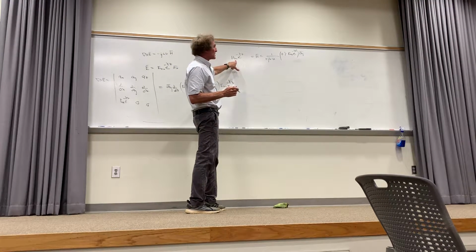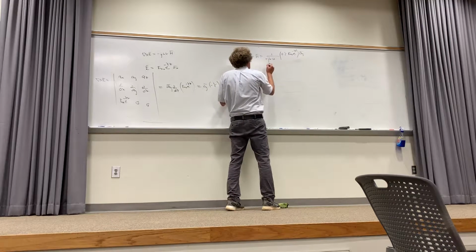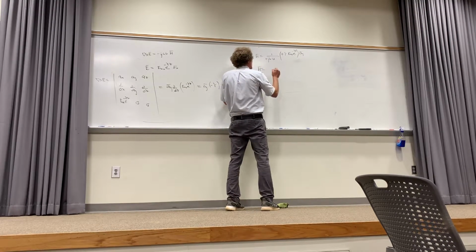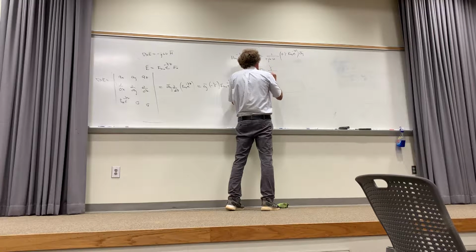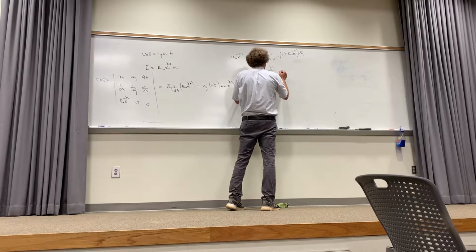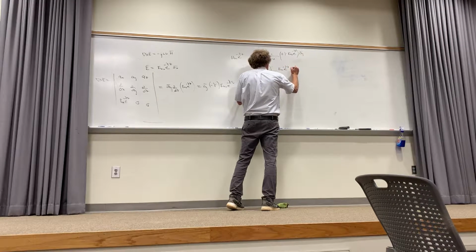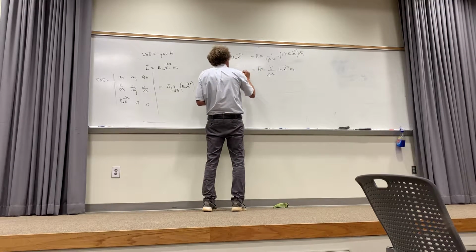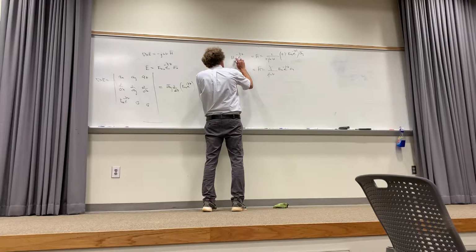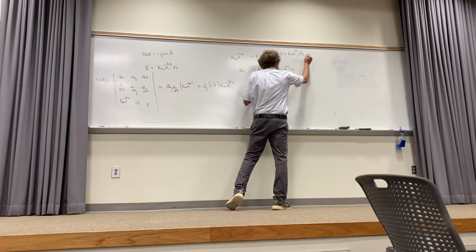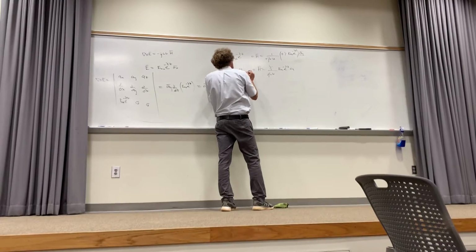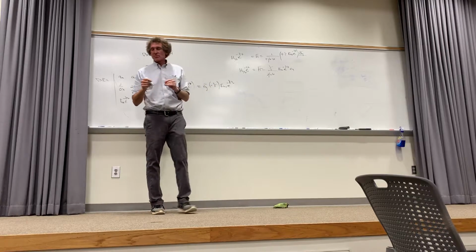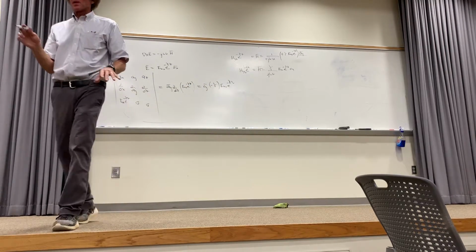Now you'll notice one thing about this. This is H right here. I could say that H itself is defined as gamma over j omega mu times the E field, but here we get into something interesting. You'll also notice that's equal to Hy, pardon. Hy is, and the reason is this is now in the y direction, Hy0 times e to the minus gamma z. Just catch your breath. I know this is a little dry until it's applied, but just work with it.